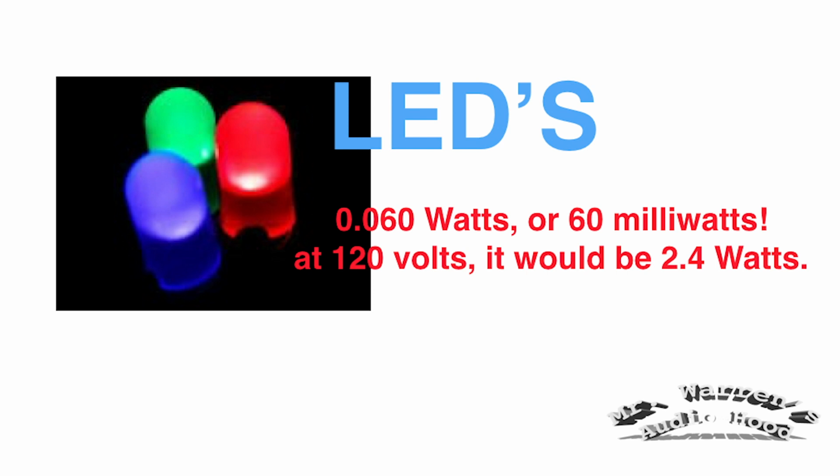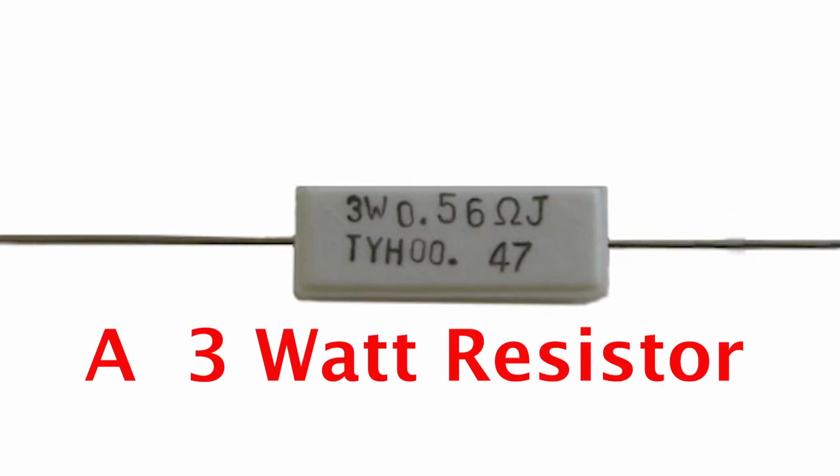The only thing we'd have to be aware of at that point is if we're using a bigger resistor in terms of its power handling capacity, it winds up being a physically bigger resistor than the common resistor as pictured. In that case, you would have to put a resistor capable of handling at least 3 watts to be safe.